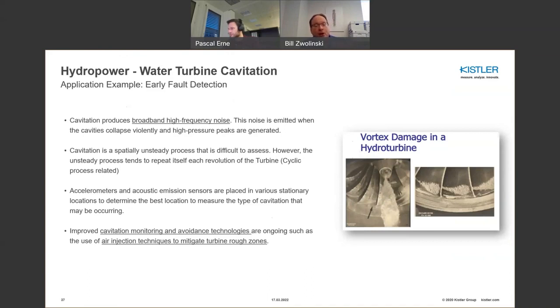And certainly part of the investigation with the USBR was looking at ways of injecting air or changing flow in terms of mitigating some of the cavitation environments. And that's really a pragmatic approach, because if you could mitigate that without losing, say, the ability to generate power, then you have a viable means to extend the life of your rotating equipment.